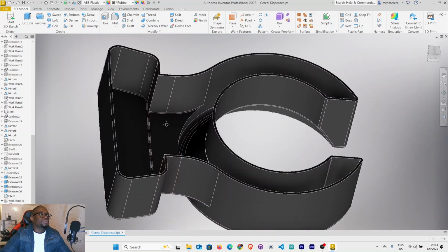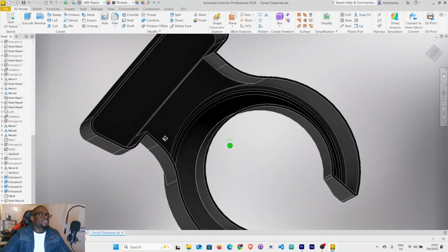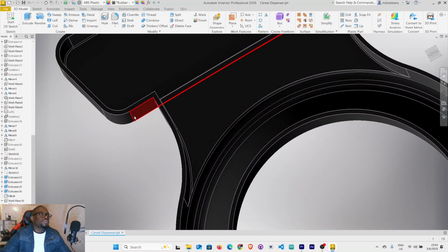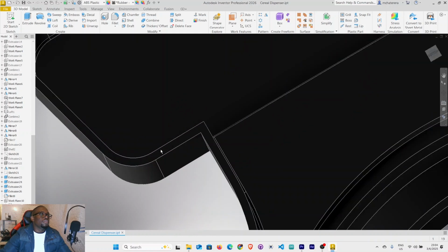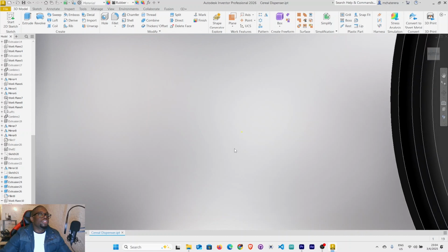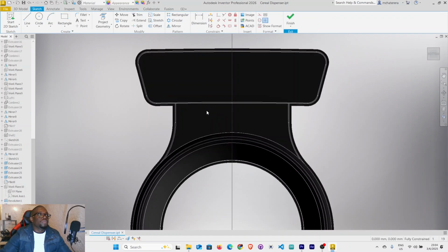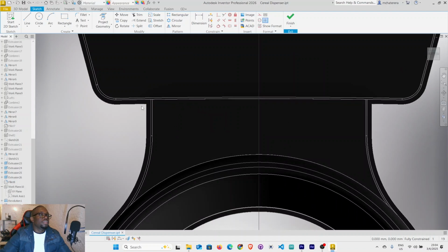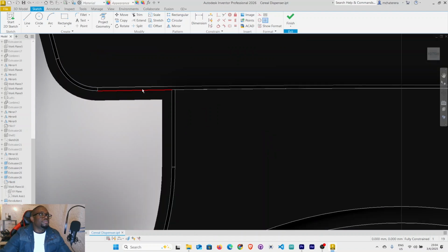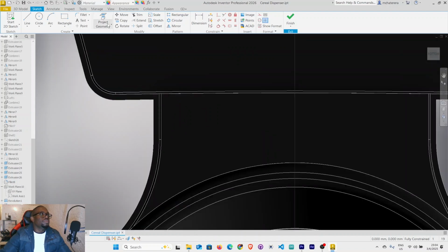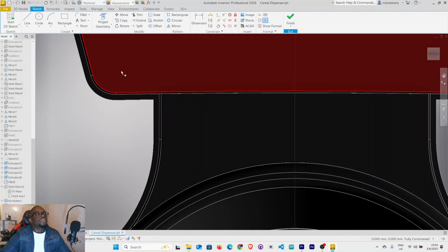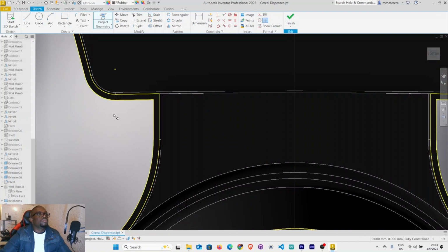Now I want to create that same wall. Click this here, create a new sketch. Yeah, it's a long process, but it will get us to the point. So let's project geometry. I want to project this profile. Right click OK.